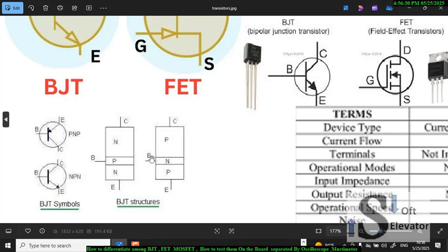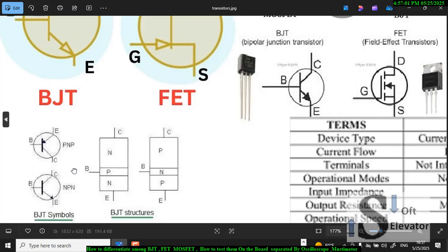And if I reverse the probes of the multimeter, so this will be the red probe, in the circuit, on the electronic board, there will be greater resistance. If it's separated outside the board, it will go open circuit. Okay, this is because this one is PNP and this one NPN.